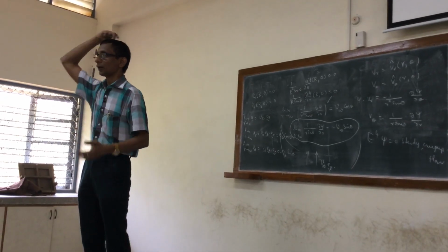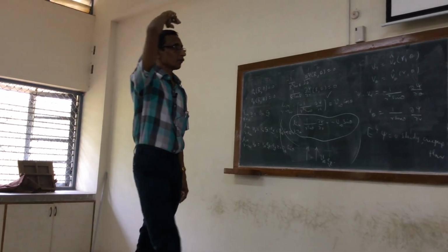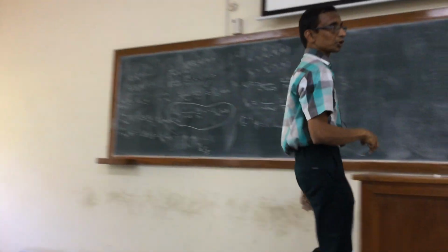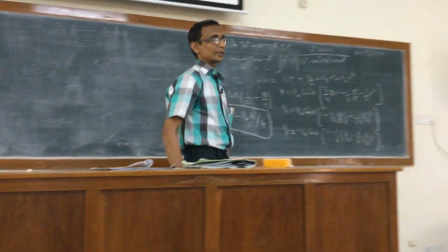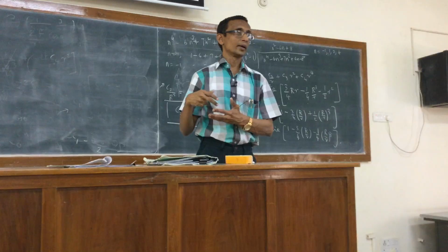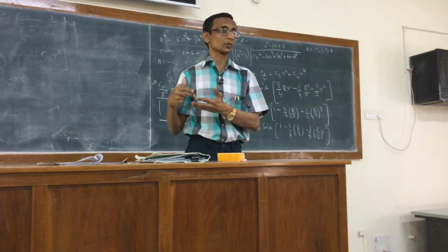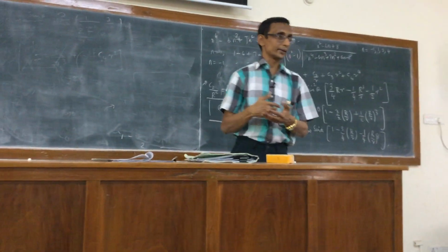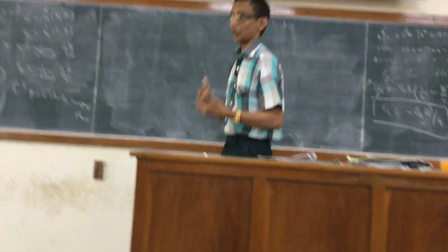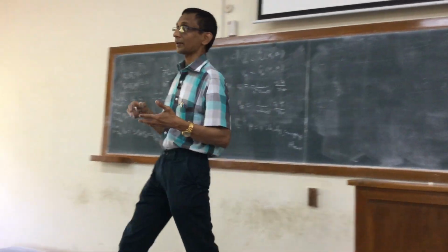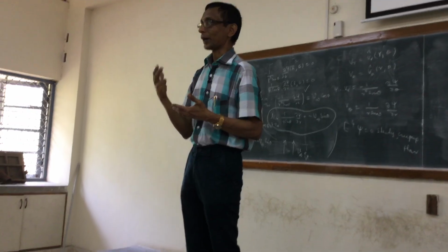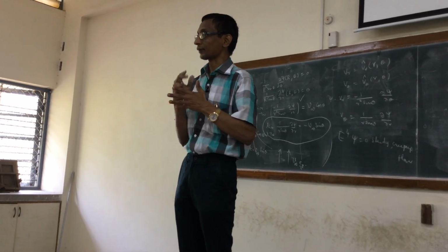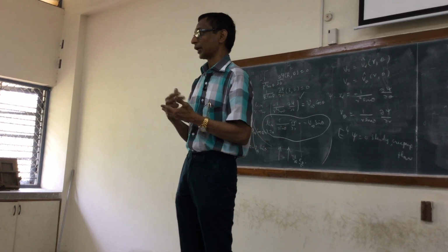When we took the curl of the equation of motion, the pressure term and the body force term could be written as a gradient of some scalar function, so that term simply cancels out. So go back to that step in the procedure. That is the basis of the decoupling.